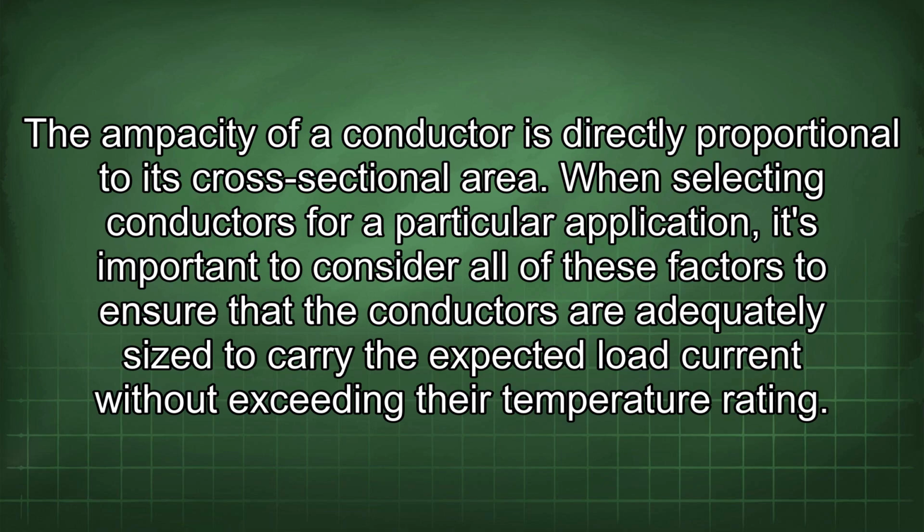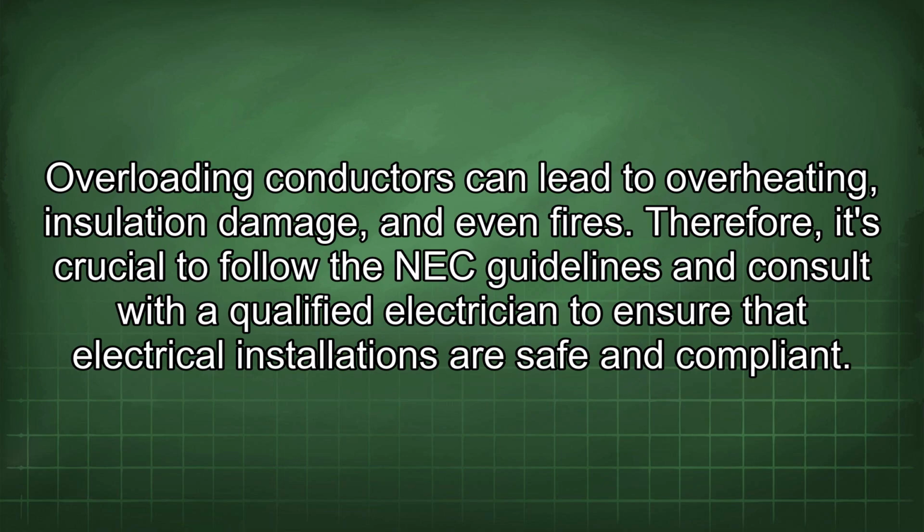When selecting conductors for a particular application, it's important to consider all of these factors to ensure that the conductors are adequately sized to carry the expected load current without exceeding their temperature rating. Overloading conductors can lead to overheating, insulation damage, and even fires.